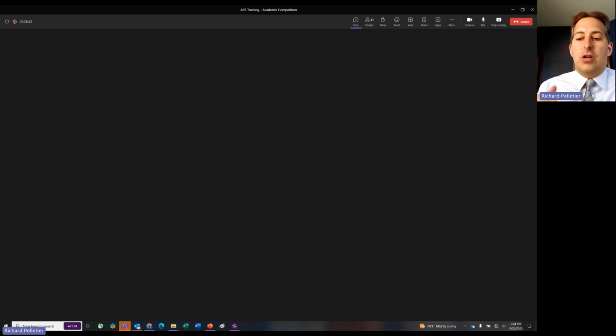If you're going to do startup and shutdown of the other systems within the software and the other model libraries, you kind of have to work within some kind of limitations. Like you can't have a true zero flow startup and then start ramping it up. You might have to start with something that's small and not zero, and work it up from there so that it can have something already in the system going.